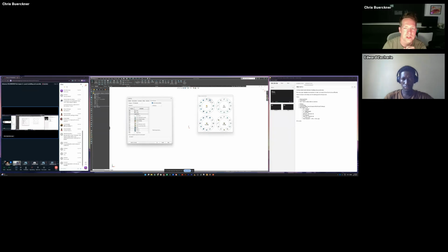And you have mouse gestures per current working state. If you're editing a part file, like adding fillets or extrudes, you can have gestures for that. If you're in a drawing or assembly, different ones for those. And in a sketch, different gestures. I've kept it to 8 gestures, and I predominantly use the gestures in sketch mode.